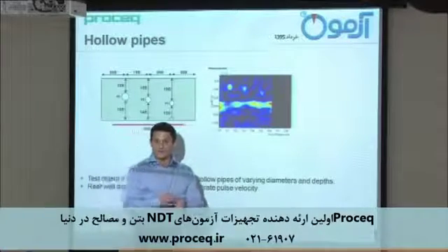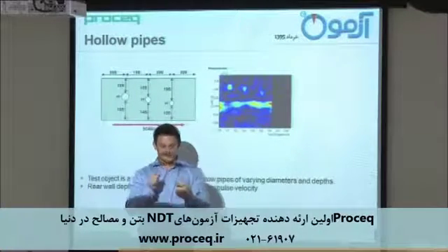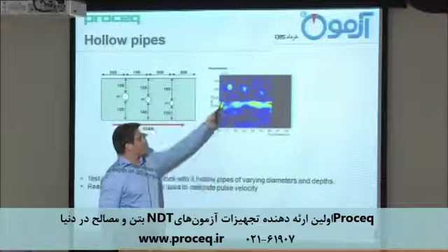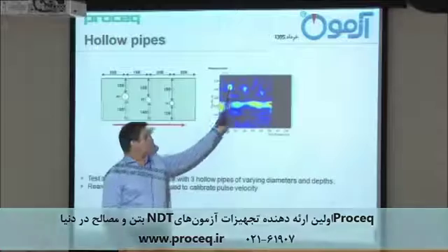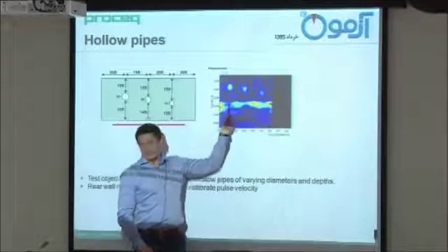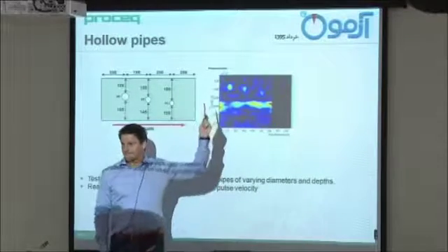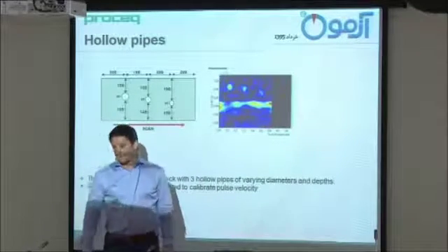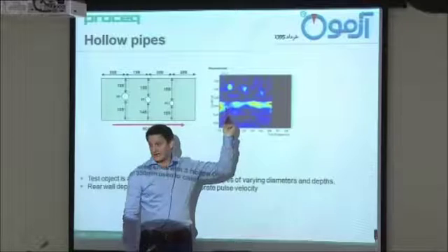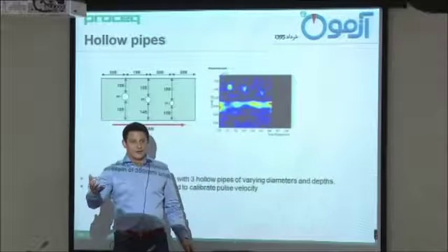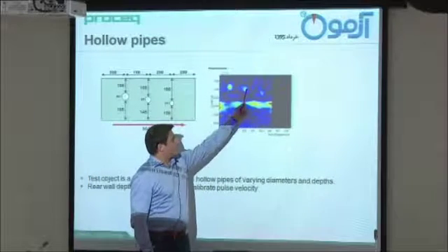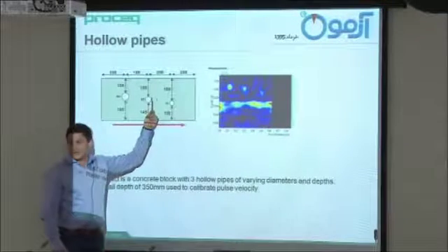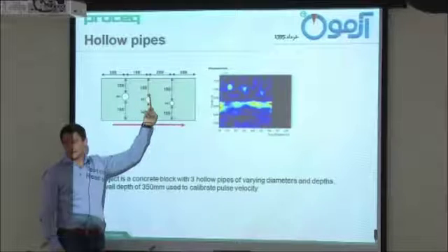So we have learned air is a big reflection. Steel is not as big. So what is good to know with this? If I have a big reflection here and I see on the back wall a shadow, it should be air. Because we know steel will transmit some way through, then the shadow wouldn't be that big. And granite the same. With the second hole, it's smaller because the diameter is smaller and the distance is longer.